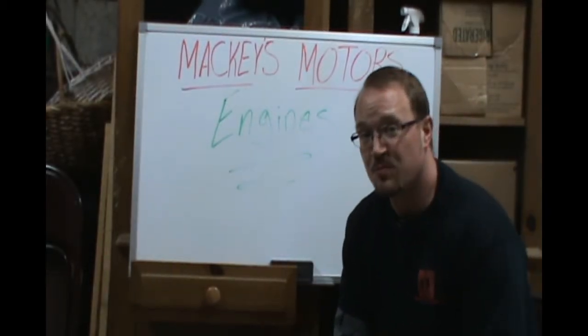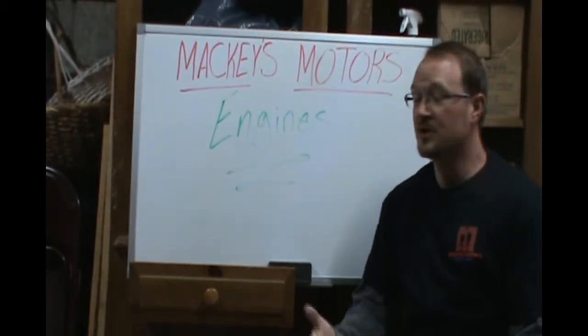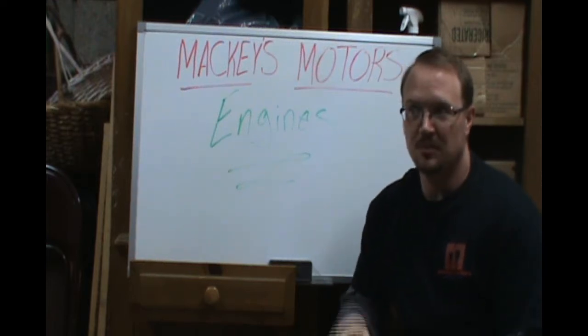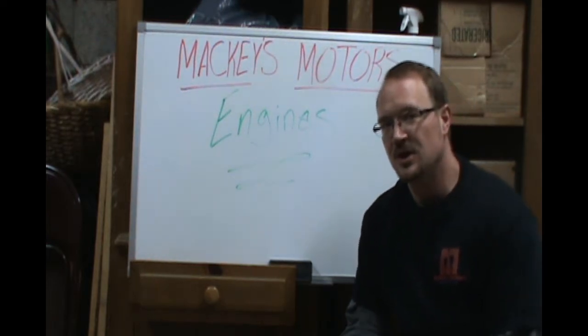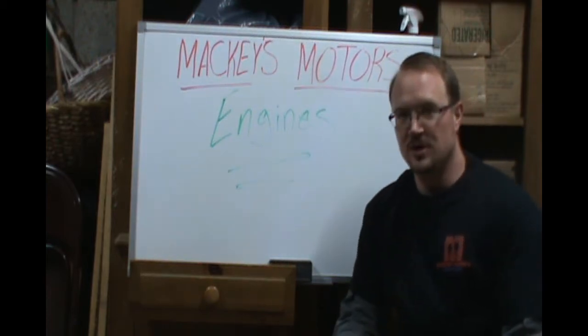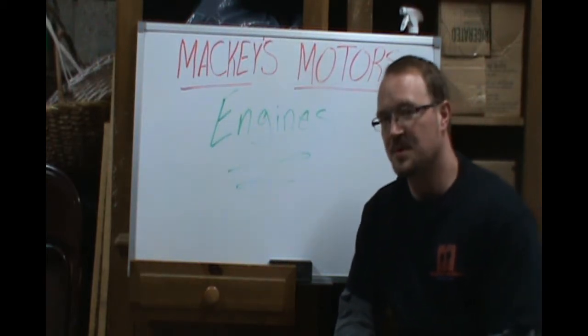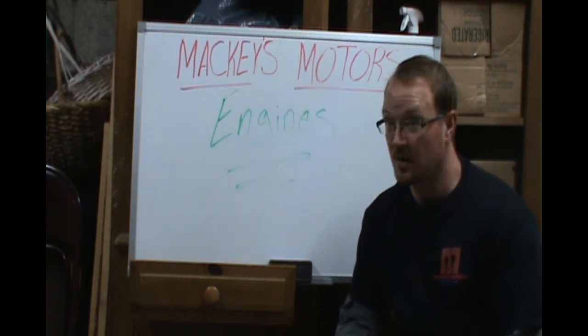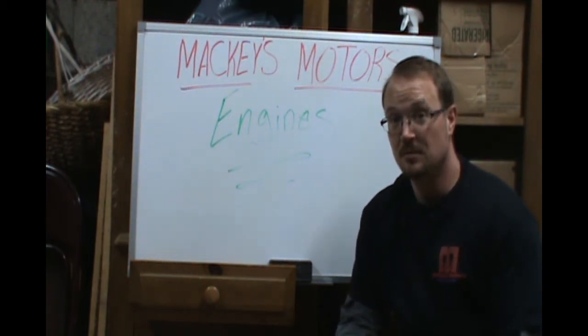So, in talking about spark plugs, we have to remember traditional tune-ups. Some people have said they have gone by the wayside, but as a mechanic you need to learn what is a traditional tune-up. And the basic tune-up components will always include pulling spark plugs and checking them and replacing them at mileage intervals proper to the vehicle.